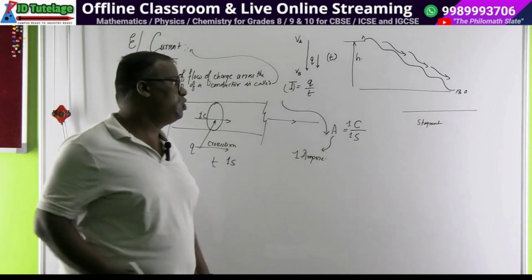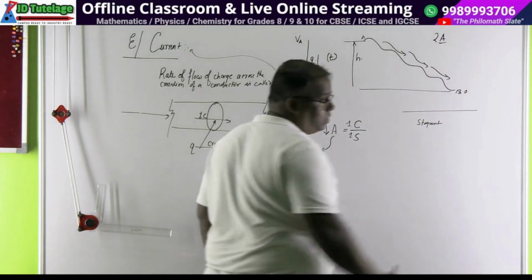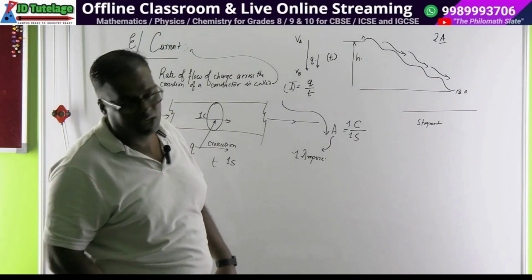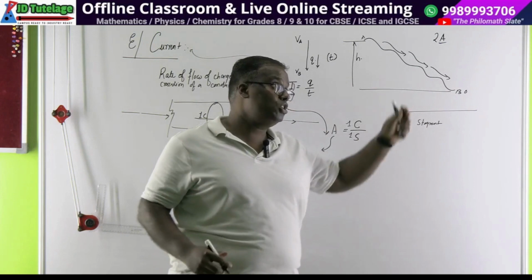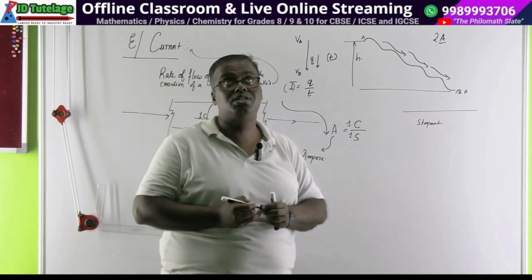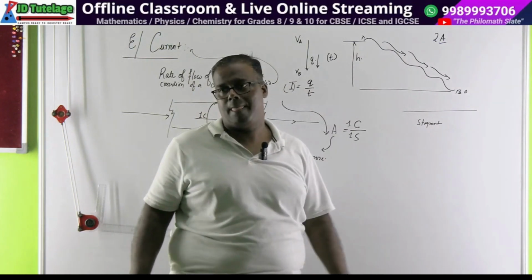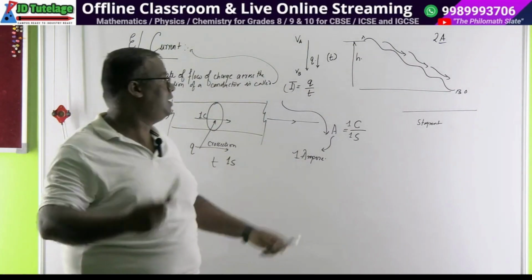So sometimes you say, you know, I've got an iPhone, my charger is 2 ampere. 2 ampere means 2 coulomb of charges flow past the cross section of your charger wire every 1 second. And the air conditioner is running and consuming 16 amperes. 16 amperes means 16 coulomb of charges. So 16 coulombs in 1 second.